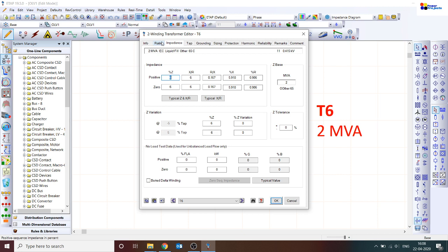So you will still be able to use this transformer designed at 50 Hertz at 60 Hertz without any technical problems, except that it increases the real and reactive power losses and the voltage drop, but it has the advantage of reducing the short circuit current. With this, you will be able to technically run this 50 Hertz designed transformer at 60 Hertz. But the question now is, shall we use it vice versa? The transformer designed at 60 Hertz, shall we use at 50 Hertz with reduced real power loss, reduced reactive power loss, and probably an increased short circuit current?